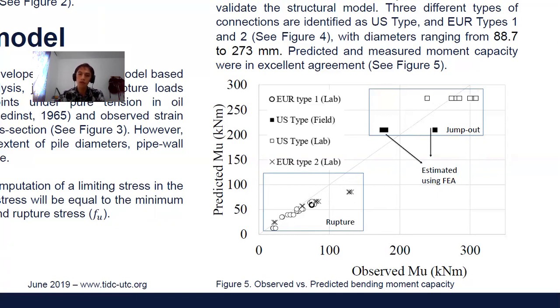So what we could extract from the literature were finite element analyses of the same tests. And because displacements were in pretty good agreement between the model and the measurement, we can believe in the moment, but still there's some uncertainty there due to the wide range of parameters that you need to calibrate for these models, with much uncertainty coming from the soil. Thus we can cast some doubt on the position of these dots in this plot, but still more or less, if we take the average, then they're kind of falling over the line.